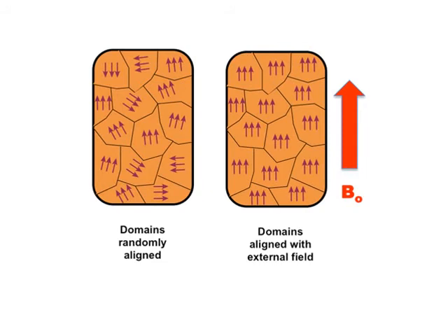If you want to magnetize a non-magnetic material, you will go from left to right. This figure you have to read from left to right. No alignment, and because of the electrical method, or another method explained for this magnet, which is the stroking method, the DC electrical method converts the figure from left to right, from non-alignment of domains to alignment of domains. It is because of an external field. The external field may be the stroking method, or it can be the field in the solenoid, which is due to DC current.